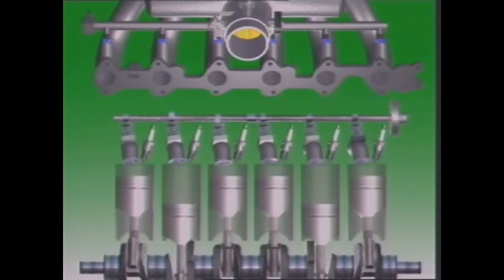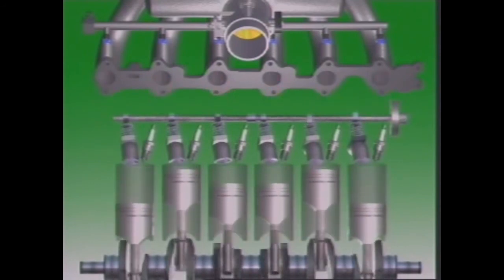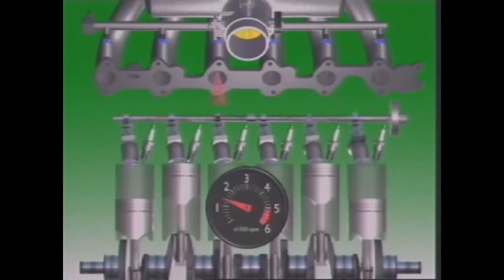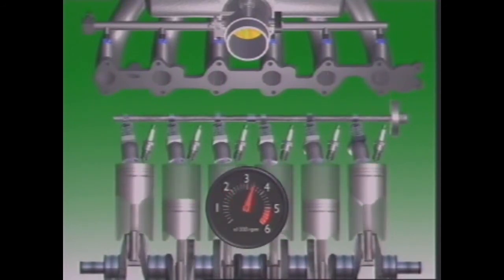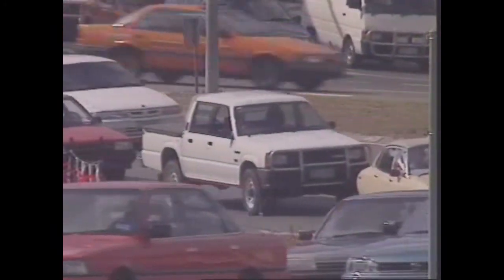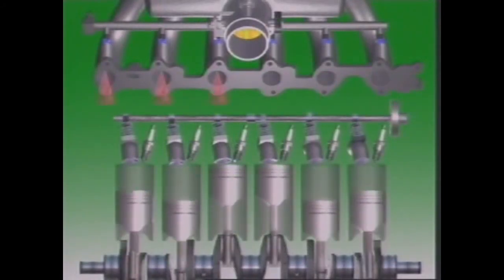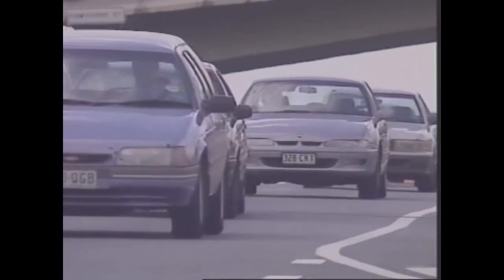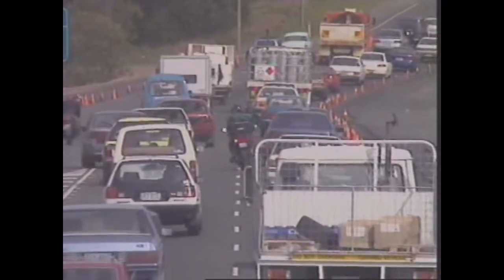In some applications, different modes of injection are combined so that the mode changes according to the operating conditions. Sequential mode may be used for low engine speeds, changing to simultaneous mode at high speeds. The same principle is used in changing from light loads to heavy loads. Similarly, the mode may change from group injection to simultaneous. Using different modes for different operating conditions makes the most of how the fuel is used, and that improves power output, fuel economy, and emission control.